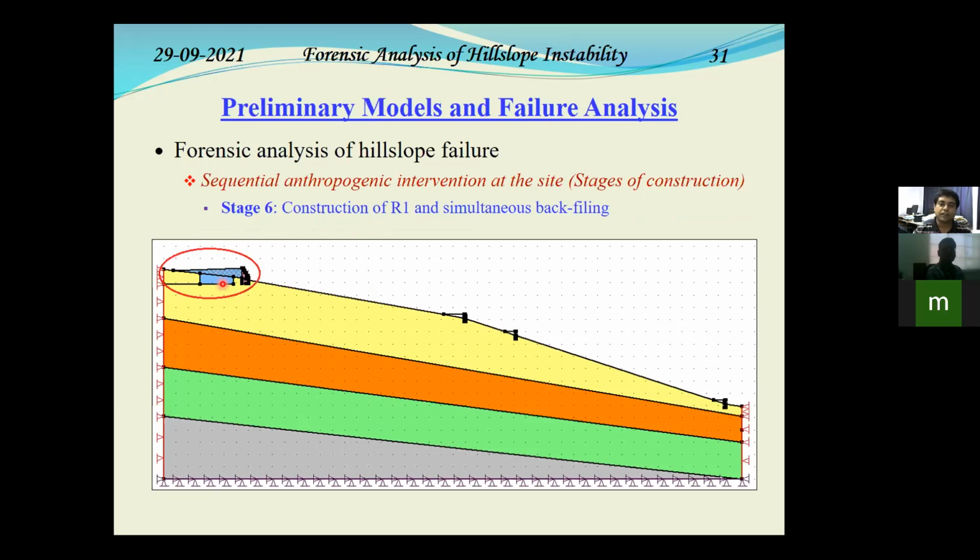Now again, there was one issue: generally we use a properly good drainage material as the backfill, mostly sandy type of material where it can be free draining. But at this site, nothing like that was done. So whatever local soil material was available was dumped and compacted, and that served as the backfill. And who knows, that also accumulated the water and gave extra thrust on the retaining wall, leading to its movement.